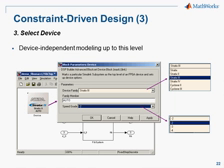Next, we would select the device. Changing FPGA device families is as simple as selecting the family and speed grade, or even a specific device. The DSP Builder tool has access to the timing models of each device in Quartus II software, which allows the tool to perform device-specific optimizations. This facilitates design migration to newer Altera devices.